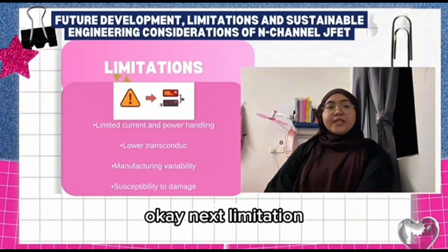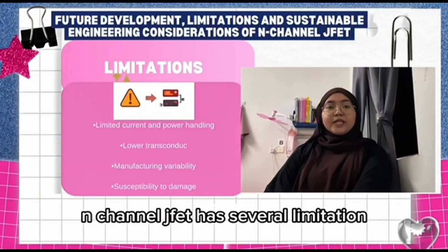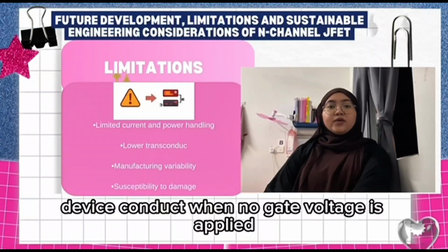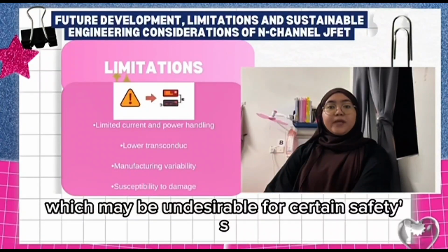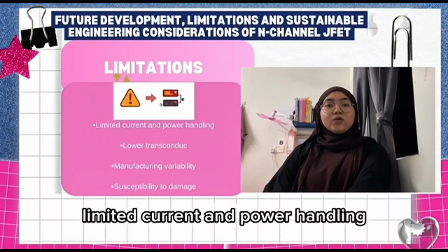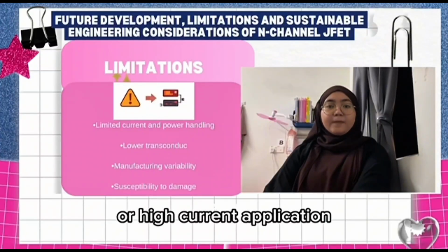Okay, next, limitation. Despite their advantages, N-channel JFETs have several limitations. First, normally on device. The device conducts when no gate voltage is applied, which may be undesirable for certain safety critical applications. Second, limited current and power handling. JFETs are not suitable for high power or high current applications.